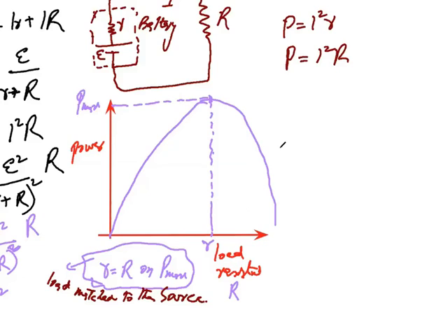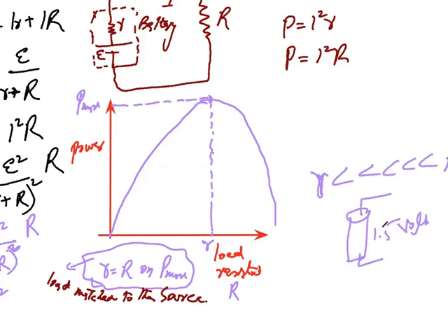Practically, for example, this can be half R, it can be 3/4 R. But this value will be much smaller than this load resistance. That's why mostly we do not encounter this internal resistance. If you buy a battery, mostly we say that the voltage is 1.5 volt. We are not talking about the EMF in this case. It means that at the terminal we get 1.5 volt. Over here we get 1.5 volt. We ignore the internal resistance because that is much smaller than this resistance.